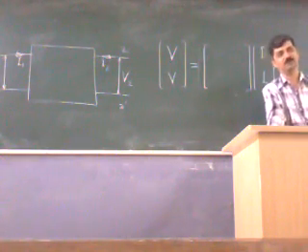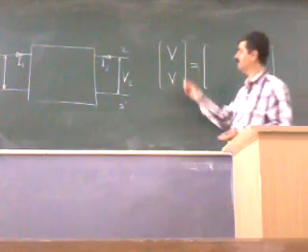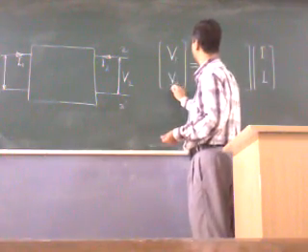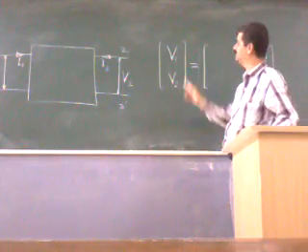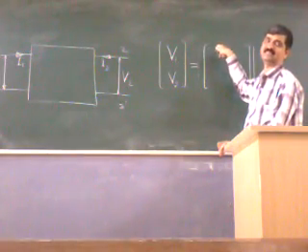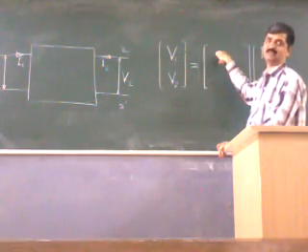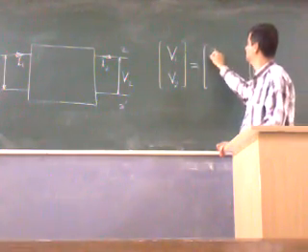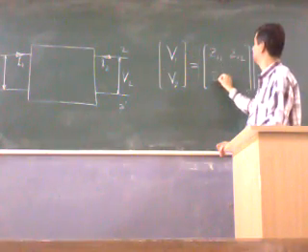Think of how many it would be, but let us start with 1 at least. So V1 and V2, I1 and I2. And since it is V and I on the other side, the thing in the matrix is Z, impedance, since V is equal to something Z into I. So it is called Z11, Z12, Z21.